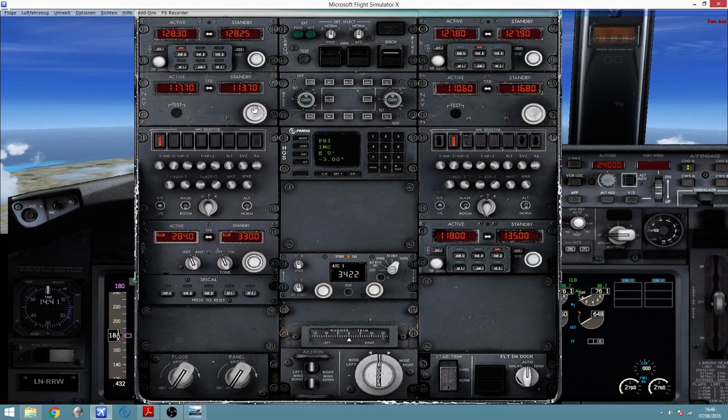Well, here you can place your mouse with the white or the shadowed hand, and each of these is going to either change the numerals or the decimals. So 116.4, I can place it here on the right hand, changing the numerals, and I set 116, and then I move to the shadowed hand and move it to 116.4. This has selected a VOR frequency on the standby window, but it has not moved it to the active window.